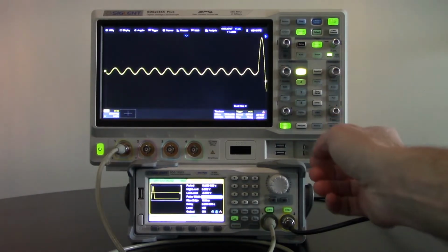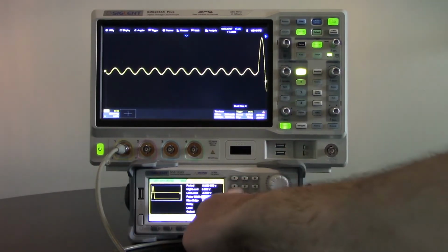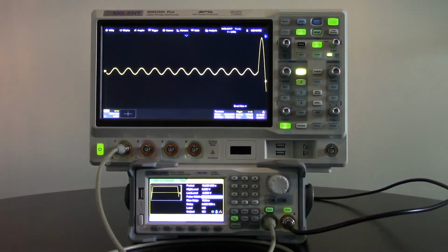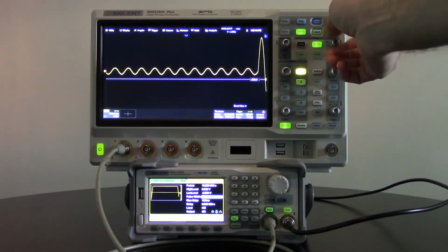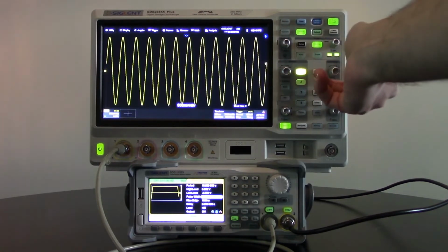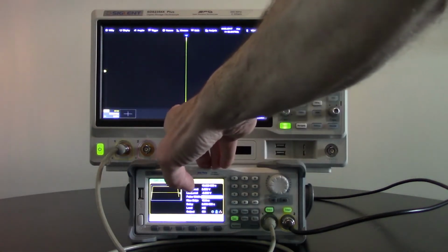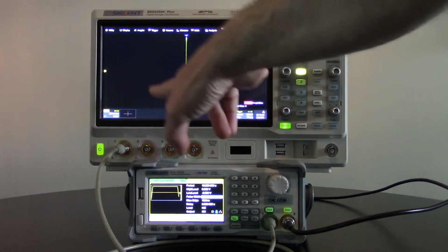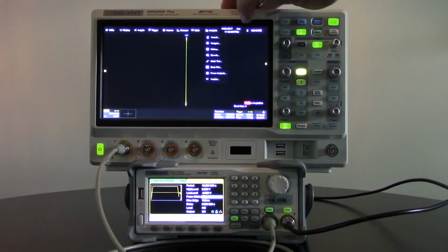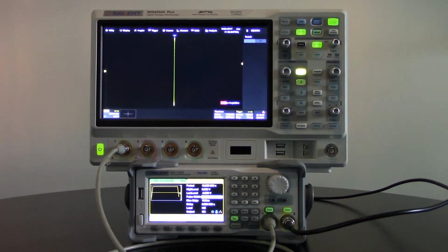And you can see here we're getting some of that showing up here, and I may have made a mistake. Oh, yep, I did. I actually want that to be 9.984 seconds, so 16 milliseconds, and we should get the things to key back up here in a moment. So I'm going to back out a little bit, and I'm going to shrink my time scale. So now this is 5 seconds per division, so I've got 1, 2, 3, 4, 5, I've got 10 divisions, so this is 50 seconds worth of data, and you'll see I'm going to disable that for just a moment. We'll let that collect data for just a moment.